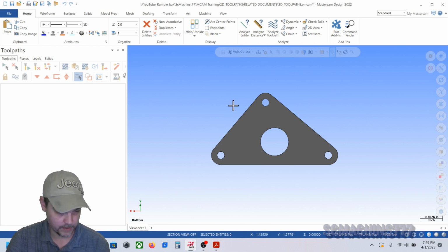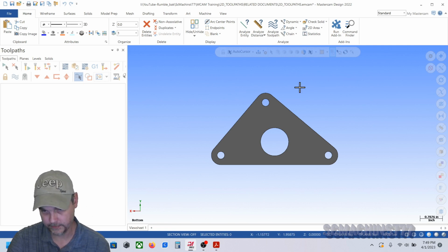If we do it all, we may just mill two steps on either side for the parallels to sit on, and clean the outer four edges up so that we can locate it on this next op.